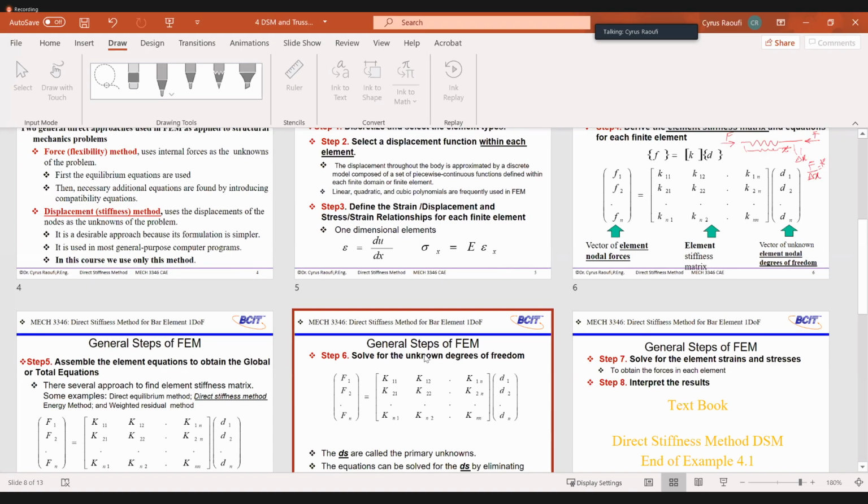Because when you get the result from physical tests, then you can say, okay, my model is correct. Then you can work on what-if scenarios in your model. Then you do not have to create more physical models. One is good enough to validate your model, but that is the best. The reality is sometimes that's not the case.